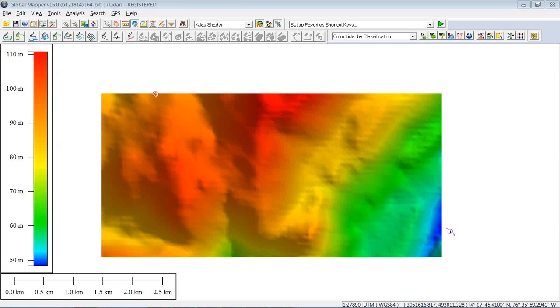And it should be stressed that we didn't have a chance to address the source file, but it was a very simple file. It was simply a tabular data set. In this case, it was a simple comma delimited data set with an X value, Y value, and then the final column was a Z value, in other words, an elevation. So it doesn't have to be overly complex. Josie was able to create a very, very nice terrain model from simple XYZ point data.